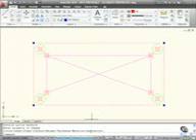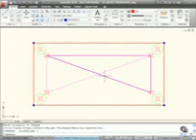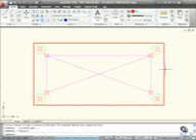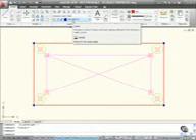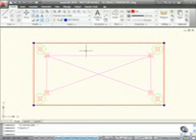And what I'm going to do is put the line weight on the status bar there. And as you can see, when I hit escape now, it's a very bold red line at 0.35 millimeters thickness. But when I select it, it is still on the rectangle layer, even though it's not adhering to the by layer rectangle properties. So that's changing color and line weight.